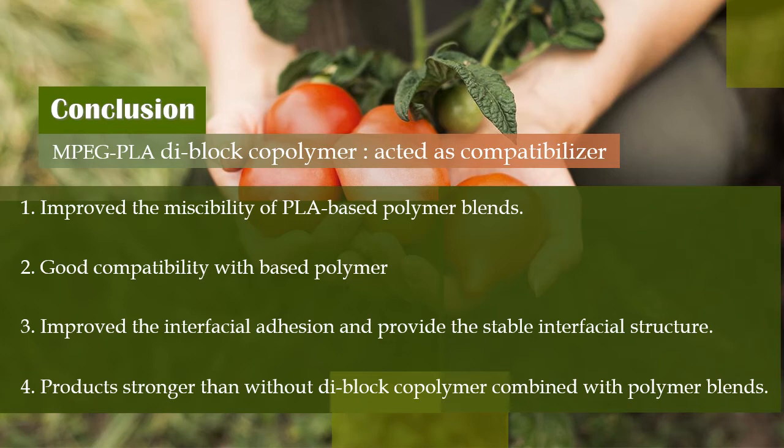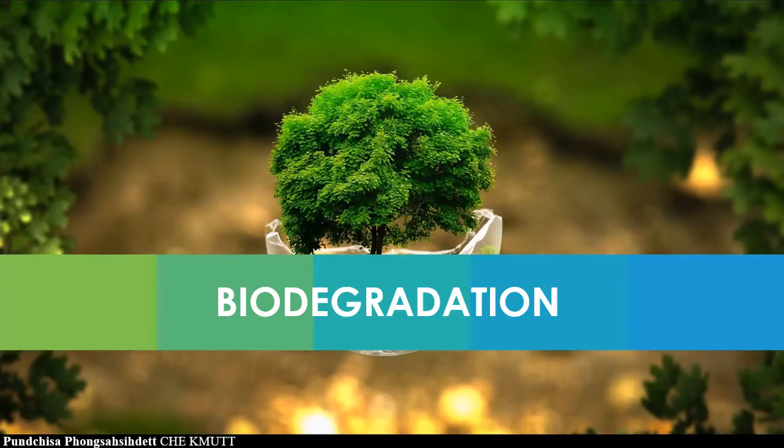MPEG-PLA block copolymer acts as a compatibilizer that improved the miscibility of PLA-based polymer blends by reducing the brittleness. It also provides a stable interfacial structure, which can reduce the interfacial tension.